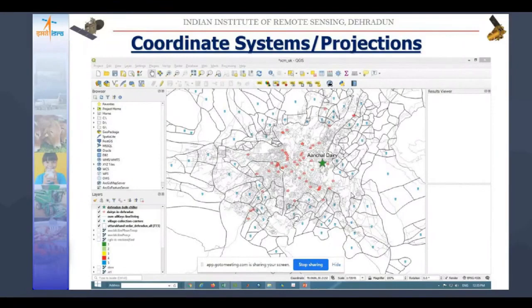With GPS, we are getting some coordinates. Now I am shifting to our GIS-based analysis. Suppose this is the dairy example you might have seen. These are the collection centers and dairies, and Dehradun, all these things. We have tagged these points using GPS coordinates. Now GPS coordinates are attached to this. Down below, if you see the coordinates, it is written 78 point something, 06 and 30.21. If you look at the bottom, this snapshot is taken from the QGIS software.